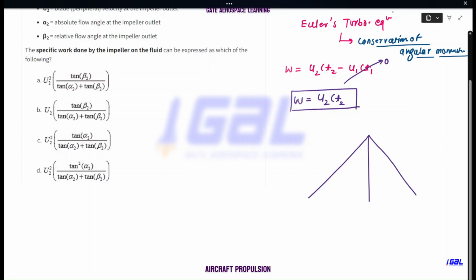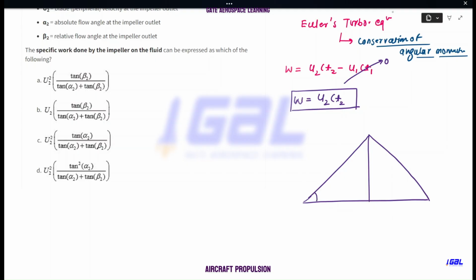Okay, anyway, so we'll draw the velocity triangle. So this is the velocity triangle of a backward curved blade, right? And this is at station number 2, guys. Okay, station number 2, that means at the exit of the impeller. Outlet of impeller, and this component is the absolute velocity, and this component is the relative velocity, and this is the axial velocity, CR. You write CR2 or you write CA2, it is the same thing, as far as your understanding, that is fine.